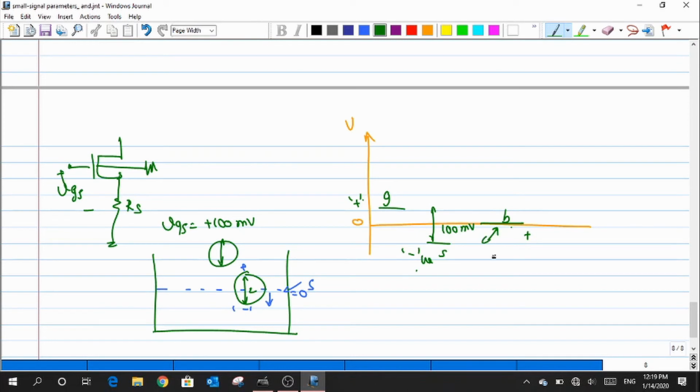So yeah, VD, that we will not consider right now. As of now, I'm talking about the phenomena in order to draw the small signal model of it. Okay. So what I'm trying to measure is whether my VBS is positive or negative. In this case it would be a positive quantity, and when I try to measure my VGS, it is still the same positive quantity. But this value is not exactly equal to my VGS. That is for sure. Okay. So it's all making sense.